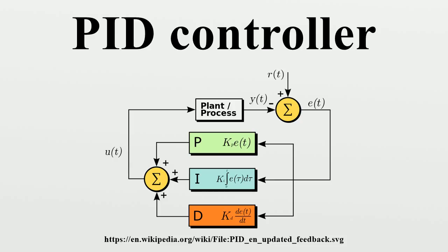If a controller starts from a stable state with zero error, then further changes by the controller will be in response to changes in other measured or unmeasured inputs to the process that affect the process, and hence the PV. Variables that affect the process other than the MV are known as disturbances. Generally, controllers are used to reject disturbances and to implement setpoint changes. A change in load on the arm constitutes a disturbance to the robot arm control process.